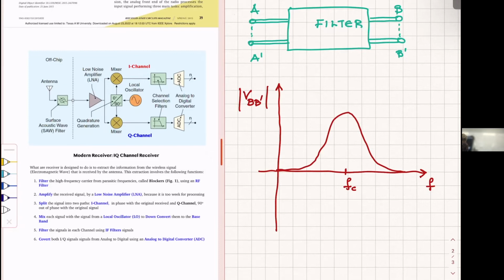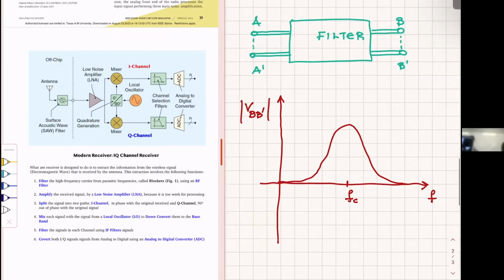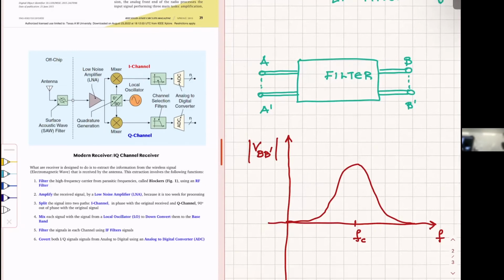So practically short here and a voltage at this point. Then what happens if there is nothing that goes through? All of your power that comes here is reflected. So in these two regions, all of your power is reflected back. It does not go through the filter, and only here it goes through. But even when it goes through, part of the power is going to go back.